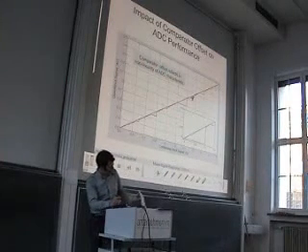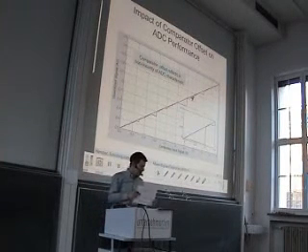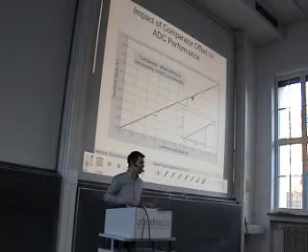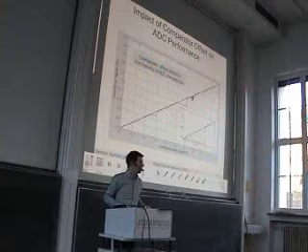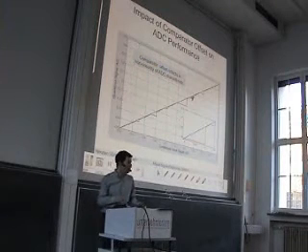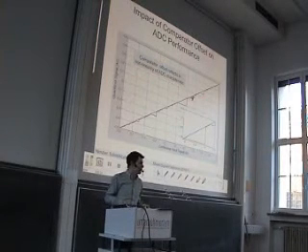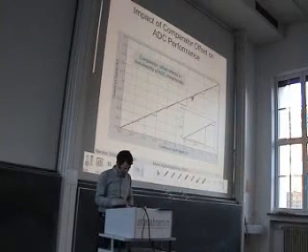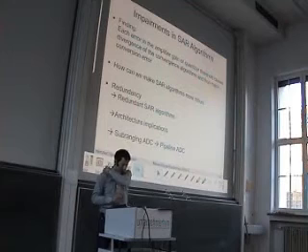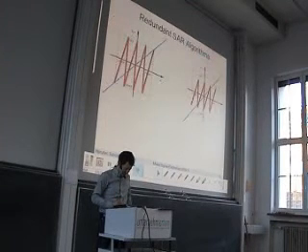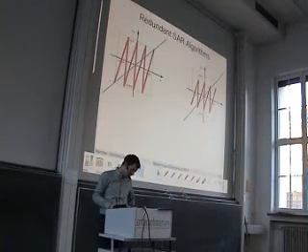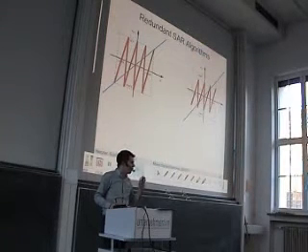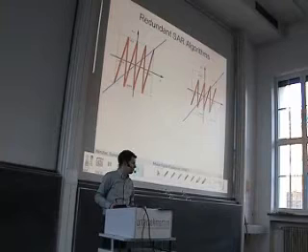So we have to find a solution that makes our conversion algorithm, this algorithm of binary search, that is quite a useful algorithm, more robust against variations. Well, then people came up with an idea for this. And this was to say, okay, what happens if we choose more than one threshold?